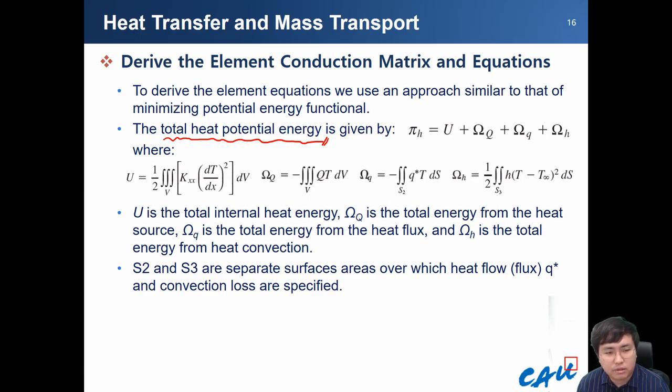If not, you can also use the Galerkin residual method. Because we already have second-order partial differential equations, without any changing of the equation you can easily derive the heat conduction equation for the FEM. However, in our textbook, they derived it using the total potential energy minimum approach.